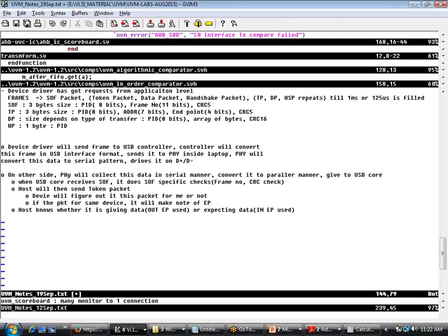In case of giving data, what endpoint is targeted? OUT endpoint. Now the endpoint number itself tells the device all this info, like the type of endpoint, the direction of endpoint, everything about the endpoint will be known only by the endpoint number.